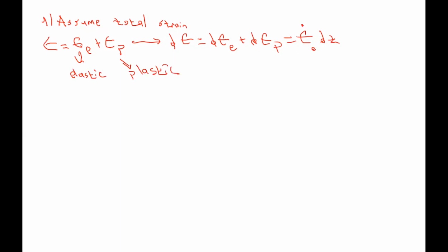And the thing is, we need to calculate elastic and plastic strains. How can we define plastic strain? Any idea how we can find the epsilon plastic? Think about the slip. Let's try to define it not by formula, but with what is the physics behind it. We need some slip, and we have a certain amount of slip planes and directions.